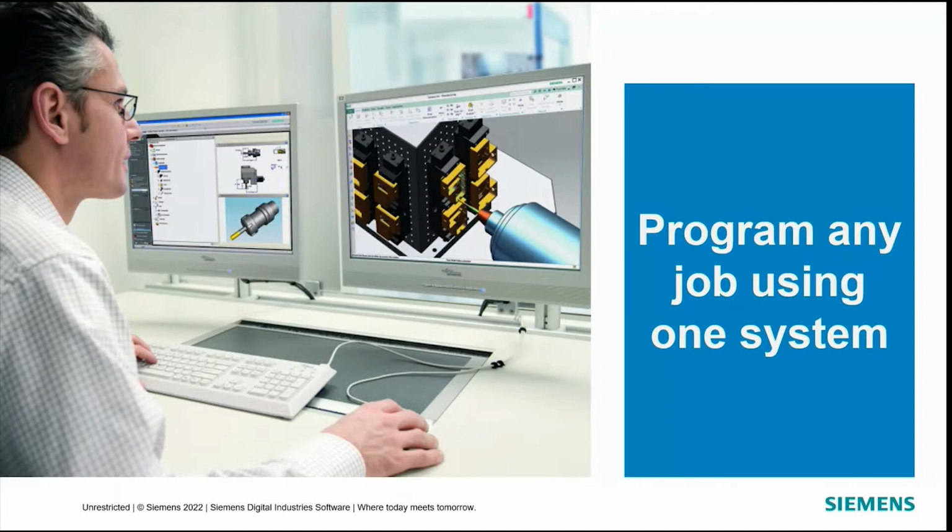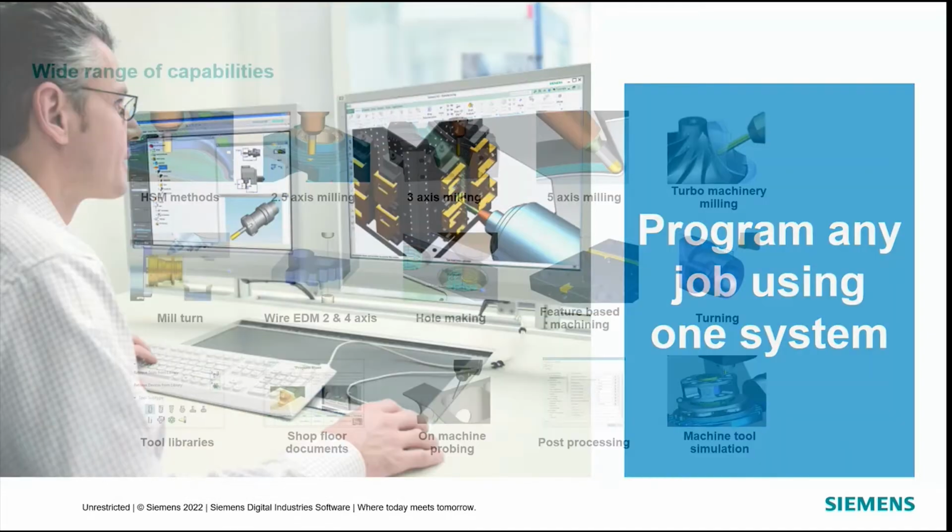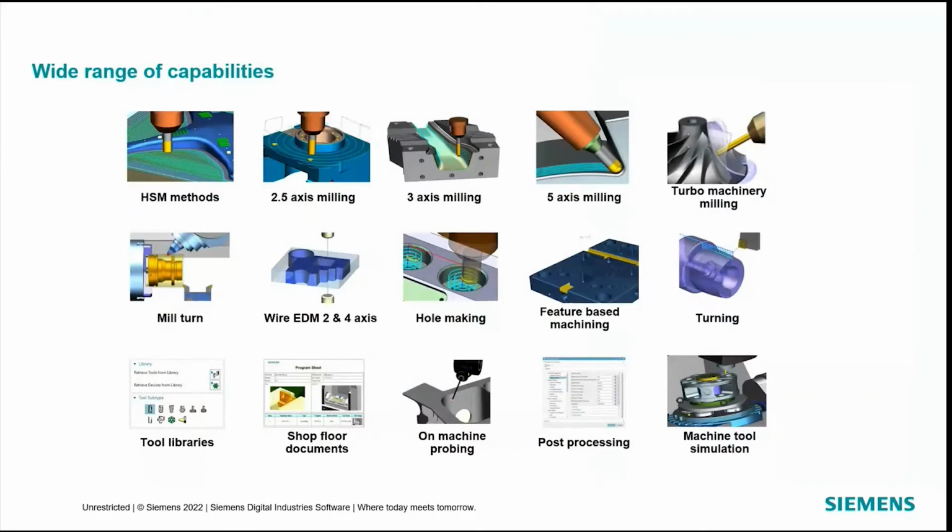It's one data set. And really that covers the wide range of capabilities inside of just CAM from a toolpath perspective, right? There's obviously 2.5, 3, 4, 5 axis. We have specific applications for just turbo machinery. So parts involved with turbine machining like that is all very automated. You can almost open the part and just recognize what's a valley, what's a blade, what's a splitter automatically, and it roughs, finishes, and provides all the toolpath there literally in a matter of a few minutes.